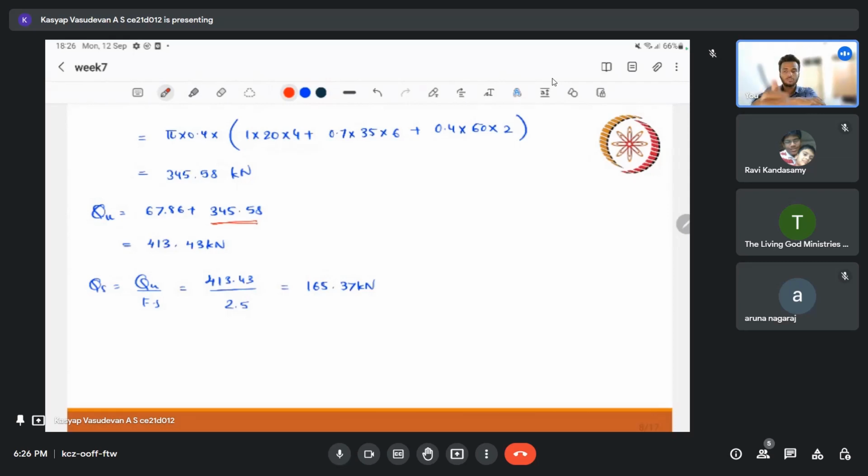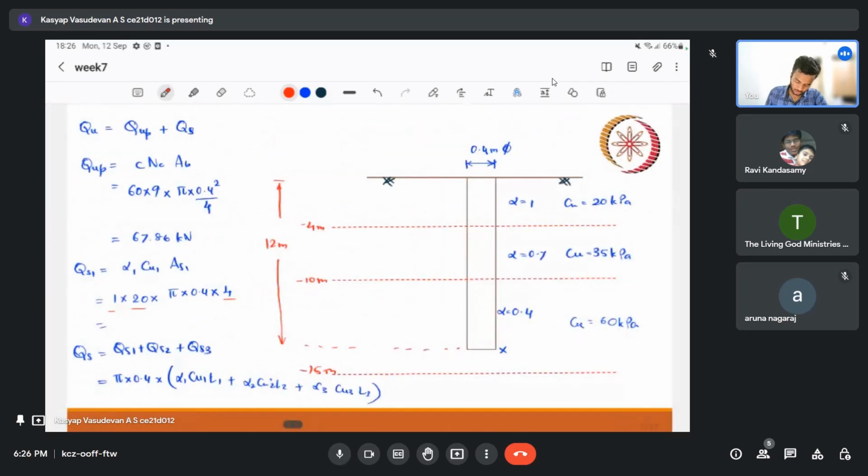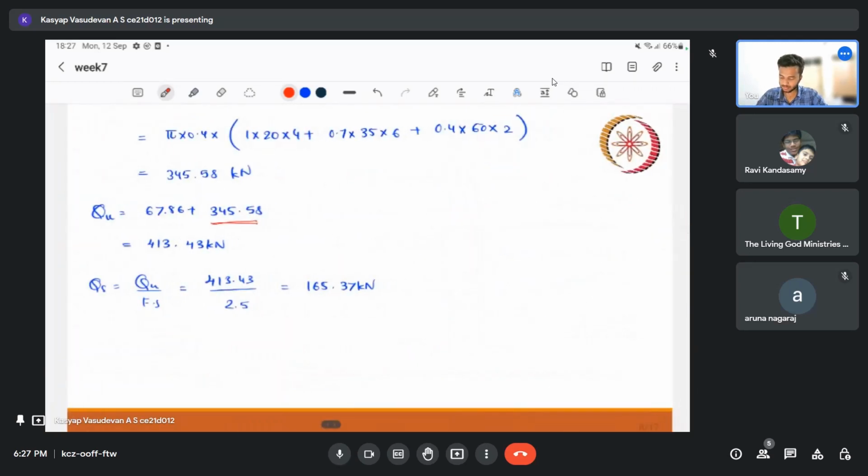So it's okay to say it's a shearing pile also, but it may not be the case for all soils, because in some soils this cu value might be too high and this bearing term could be higher. But in this particular case you can observe it's like 5 times more than our bearing resistance. So you can see how important the shearing surface is in contributing.